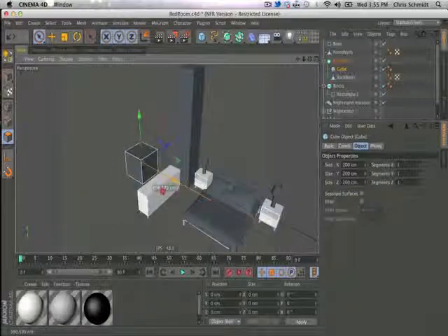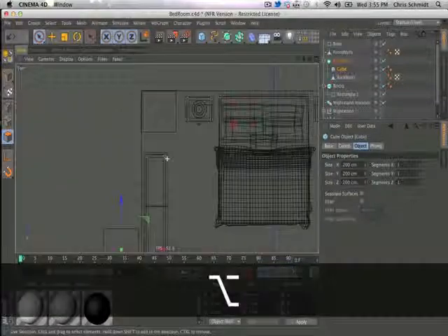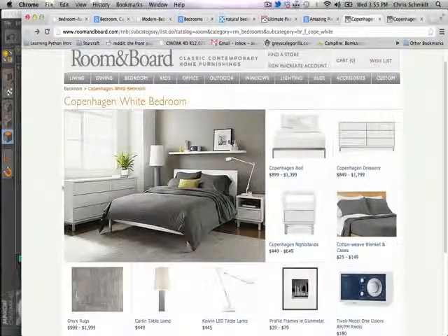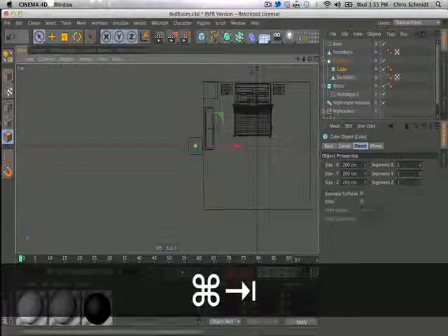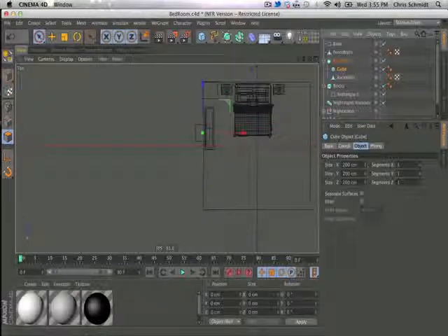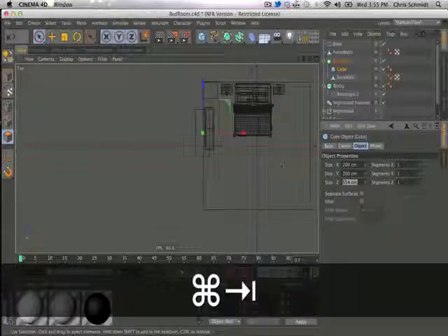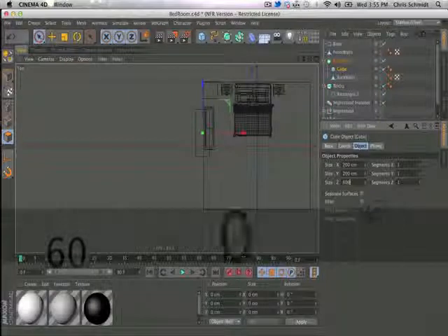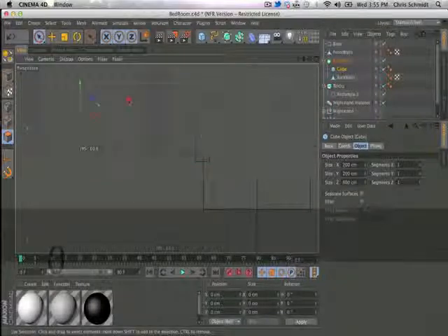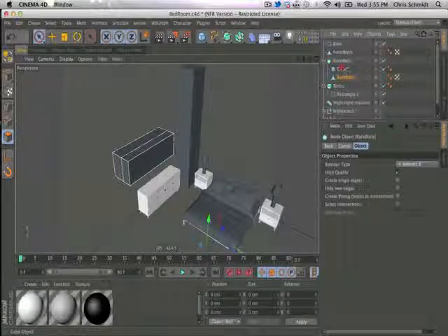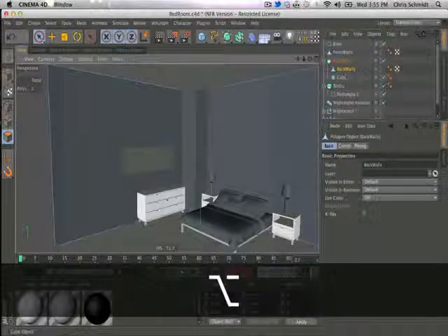I can drag the cube over. And let's go to top view. This window looks like it's actually a little bigger than this cabinet. So let's move this to about what the center point of the window would be. We want the Z to stretch out a little bit. Where does it start? It starts right about there, I guess. Let's use round numbers. And this should actually be A subtract B, so we have to rearrange this. There, boom, hole in the wall.